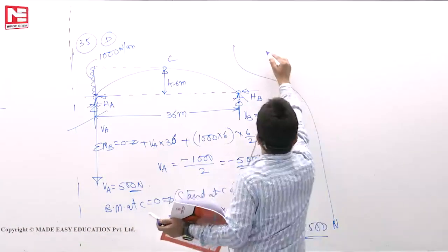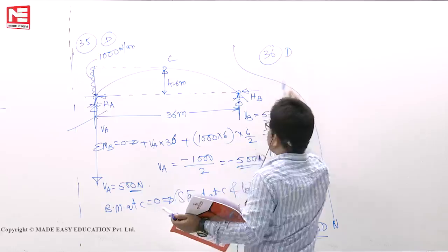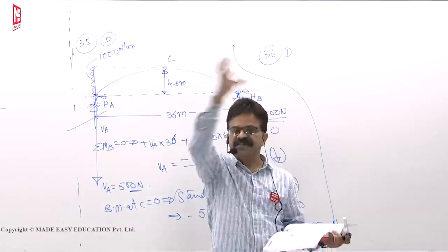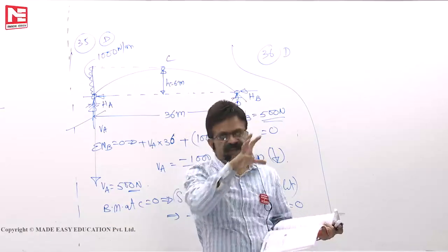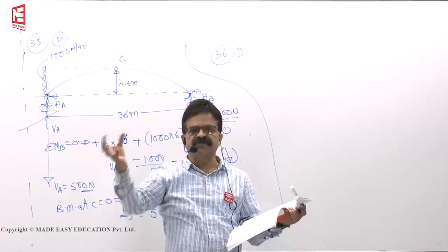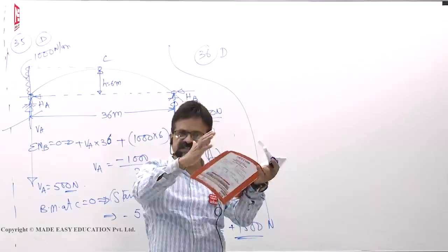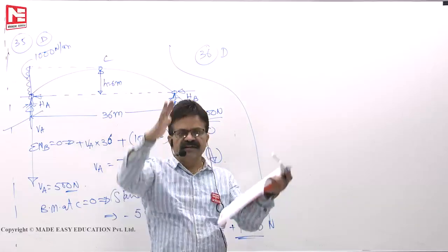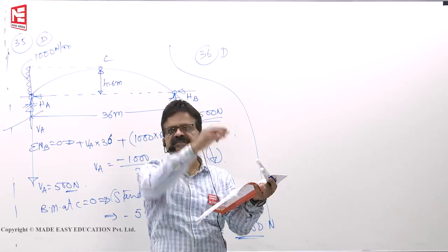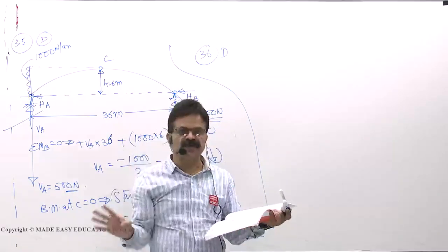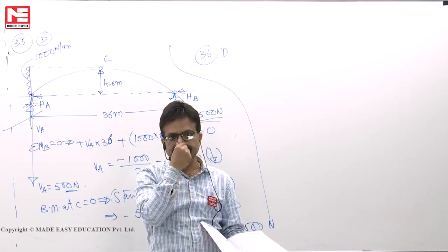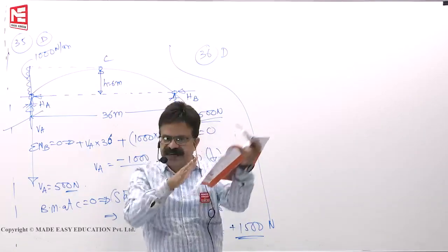That sixth question, D. In the olden days, in stone construction, when you see the forts, etc., arches, you will see that the stones are simply laid in a circular arch type. Whatever the stone crushing strength is, that is the strength of the arch. If the stones crush by direct compression due to axial thrust, then the arch will collapse. So, the strength of the arch is the strength of the stone itself. No shear, so no question of sliding.